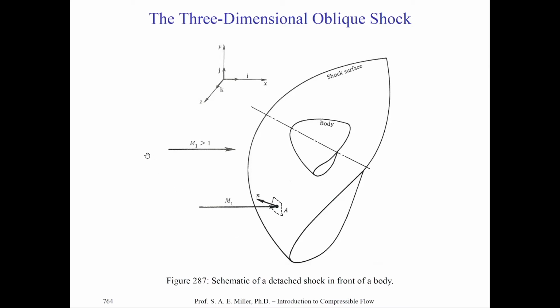We once again have a supersonic Mach number coming in, and locally, we might view, if this is at an angle of attack, the incoming Mach number from left to right, and our body's going at a large angle of attack, or yaw, relative to the incoming flow direction. This incoming Mach number might hit a differential element dA, with an outward pointing normal defined from the outward normal of the shock, M1 into the vector location with normal vector n out unit.